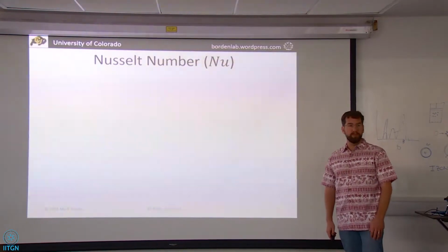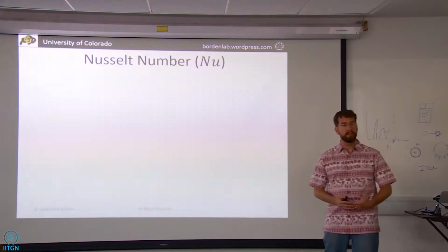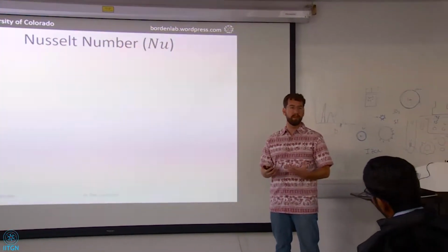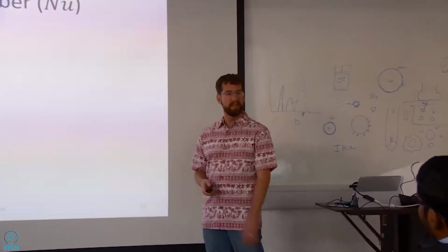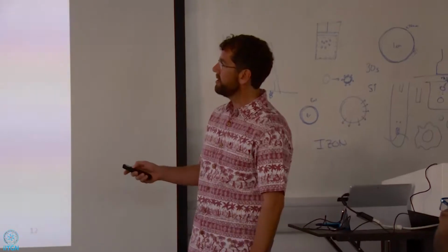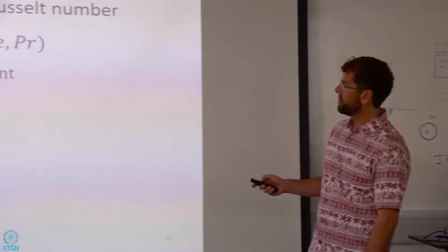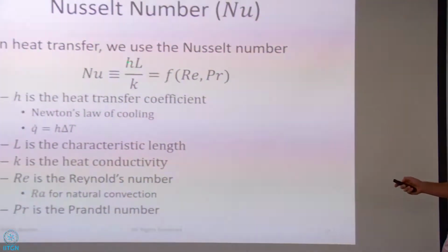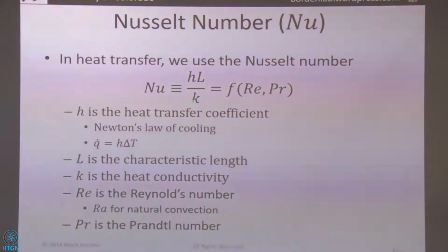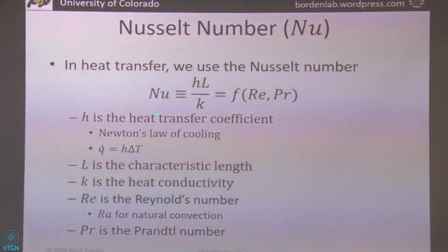Another important concept is mass transfer. In engineering, we like to use these non-dimensional terms. Since I often have mechanical engineers, I'm going to introduce the Nusselt number and the Sherwood number. The Sherwood number is what we're going to use, but the Nusselt number is for heat transfer. It's an engineering number, but it's really useful because it relates the heat transfer coefficient, h, to some length scale and a thermal conductivity. Actually, this is thermal conductivity.